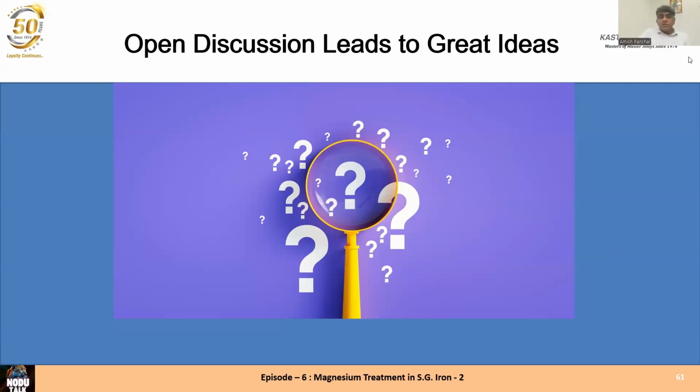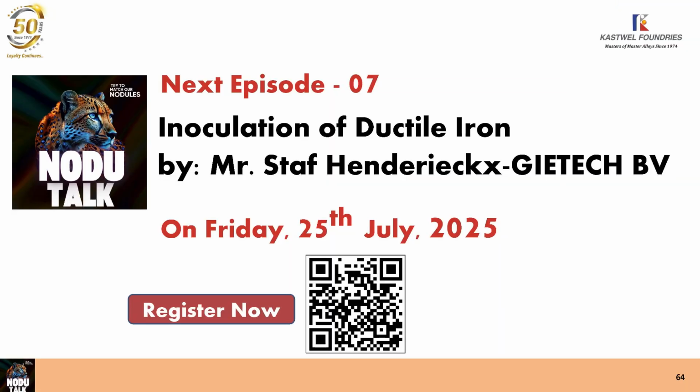Okay, so basically the more calcium, the more liquid slag generation. Yeah, but you can also remove the liquid slag by a good slag coagulant, as we say. But ask your supplier of the coagulant which one you need to use when you have calcium. And in that way, you can make the slag solid so that it can be removed easily.